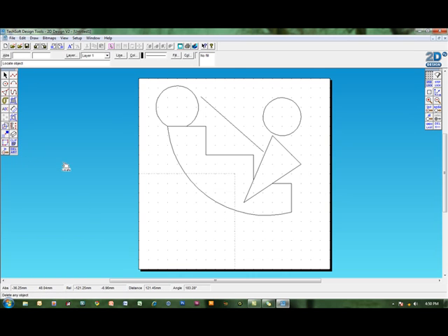Now the last thing I just wanted to show you in this tutorial is how to control some of those measurements. I showed you before that, for instance, a line, if I know my grid's 5mm by 5mm, I know that if I count across half, 1, 1.5, 2, that's now a 2 centimeter line. Now I'll create that line. Now if I select that line and then I go down, what I want you to watch is down this section of the screen. So I will say relative, absolute, and it will give me a distance and an angle.